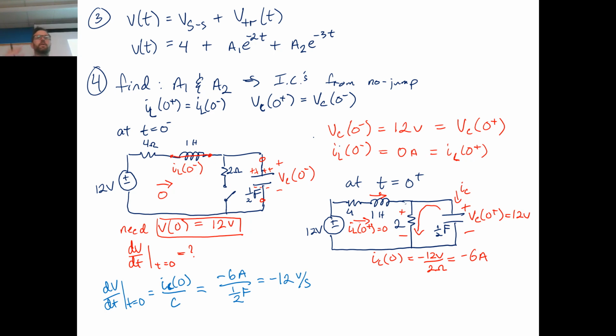Capacitors behave as opens, inductors as shorts, and you're just finding these small little parameters there. You're using the fact that the inductors and the capacitors get stuck in whatever state they're in between the switching events, and that turns this RLC circuit, whatever it is, into a much easier to solve thing. You don't even end up doing mesh and nodal, you're just figuring out by inspection where things go, and paying attention to the nitty-gritty details like directionality.